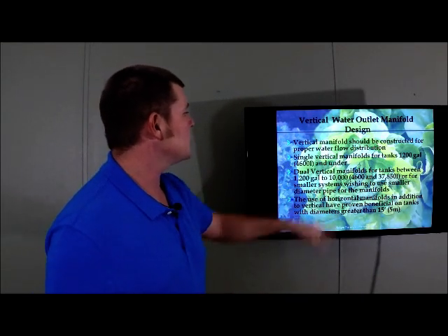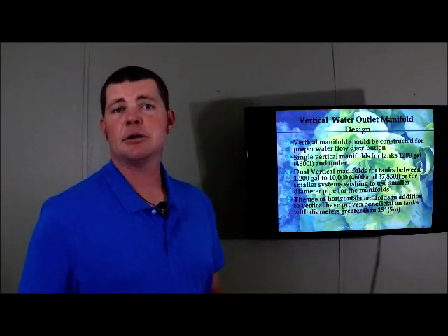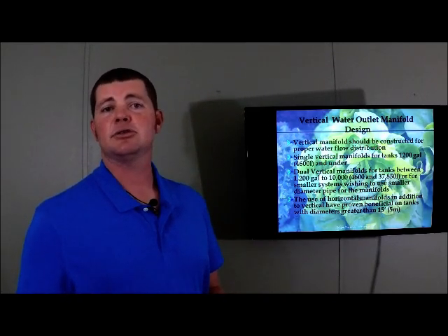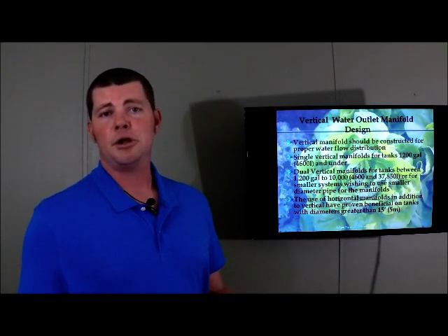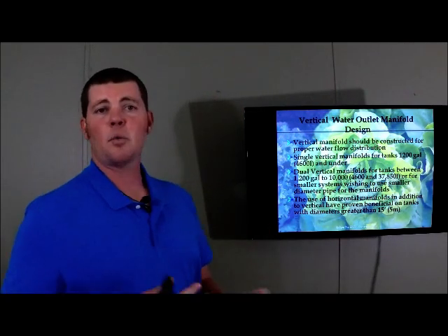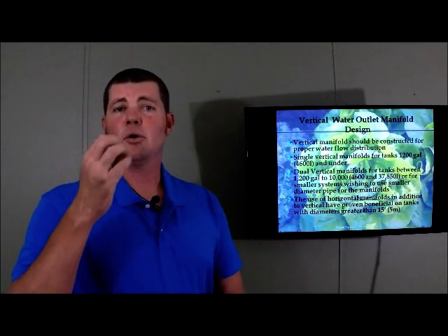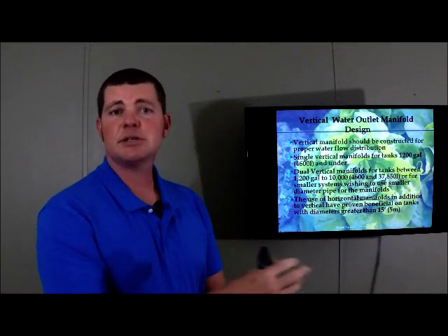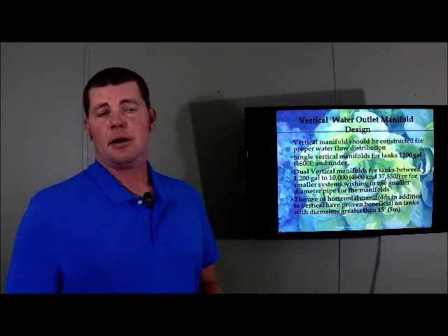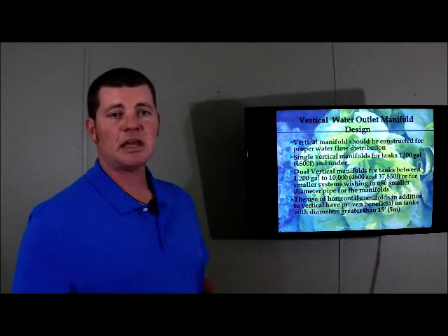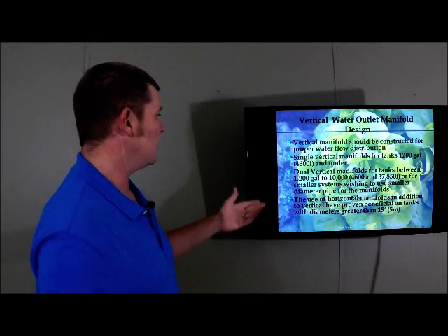Or you can do these for smaller systems when you don't want to use a large pipe in the tank. So say you're doing a backyard system and after you do the calculations, it tells you it should be a 2-inch pipe going down to the bottom of the tank. But maybe you only have 1-inch pipe. Well, do the calculations for 1-inch pipe, and after you do them, I'm sure you can figure it out. It will tell you that you can have one manifold on each side of the tank. You drill the holes, you get the flow rates that we're going to go through here. But basically, I would just say small tank. If you really want to use small pipes, you can do that. I think it's easier just to use a single manifold.